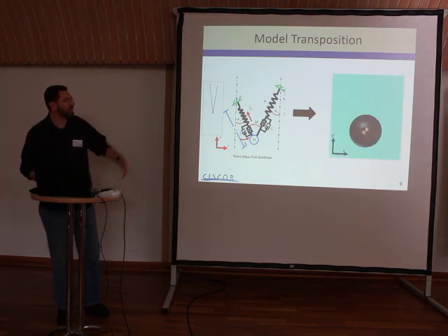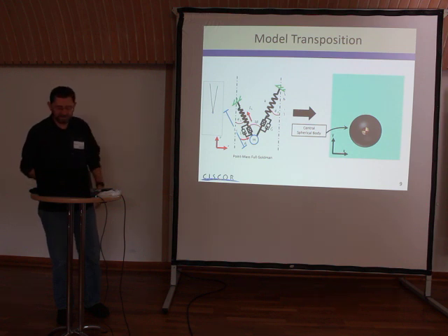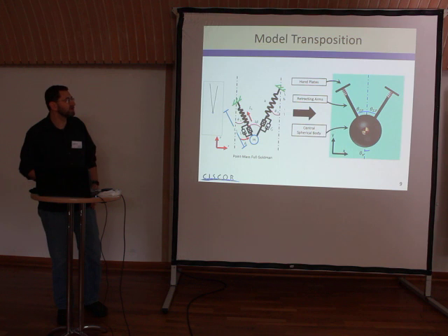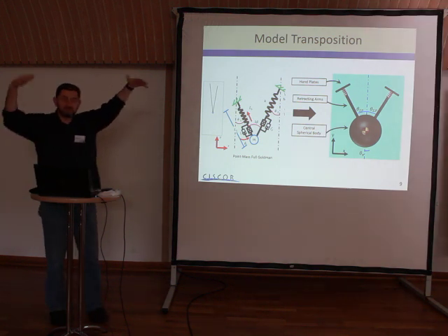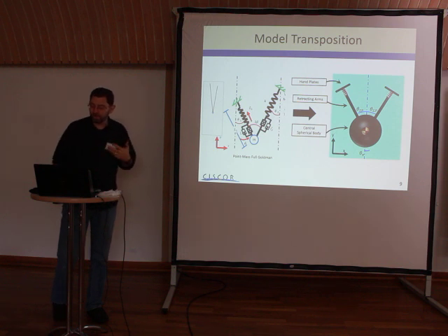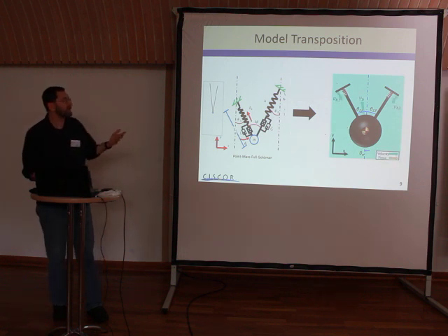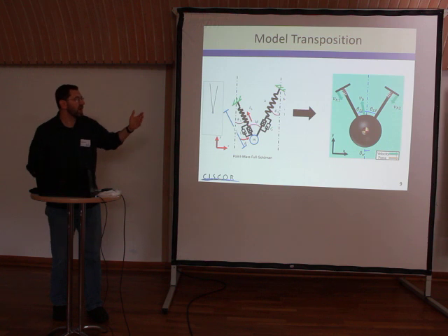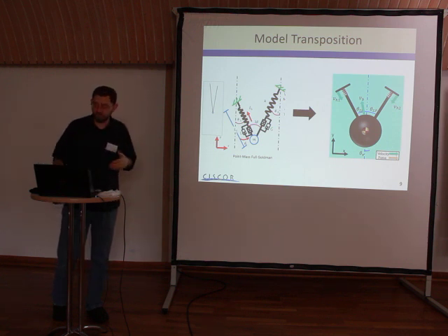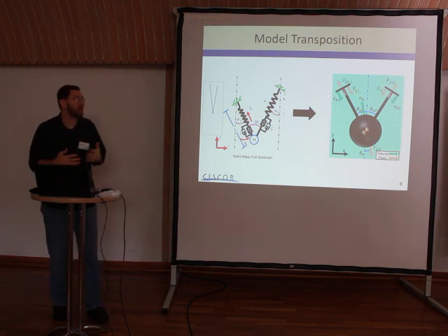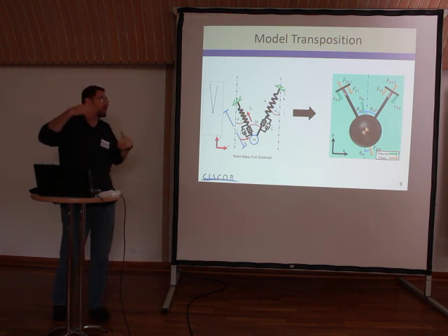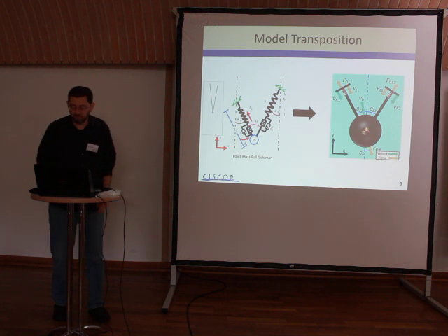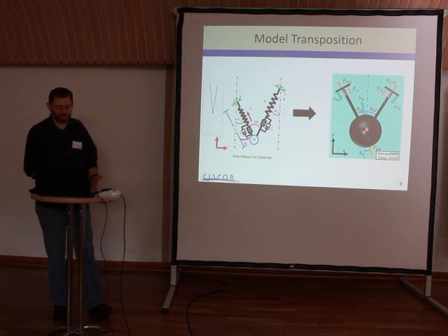And so we've translated that to the aquatic environment by having a centralized body that has mass, treated as a sphere. We have two limbs. Each arm can retract. Each hand has a sort of plate which can pull against the water. Then we look at the forces, the velocities of the hand and the body relative to the fluid, which allows us to compute drag-based forces from the hands and the body on the water, as well as the springs or the internal motor forces of the robot itself.